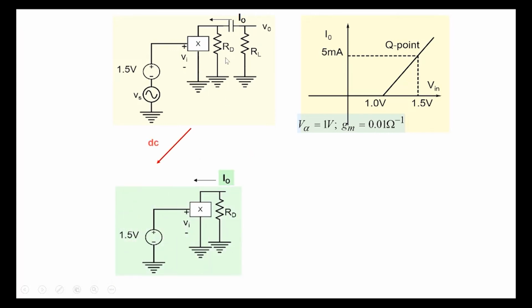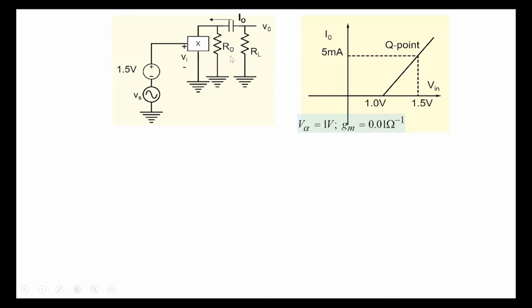So what we are finding is that in general, when we build amplifiers, we'll have biasing voltages which are DC in nature. And the signal for us would be whether it's speech or video, and for simplicity of discussion, we'll take it as a sinusoidal, so it's an AC signal here. So the analysis of our amplifiers, we can break it up into a DC analysis, and we need to make sure that the DC voltages are appropriate and there is a path for DC currents to flow.